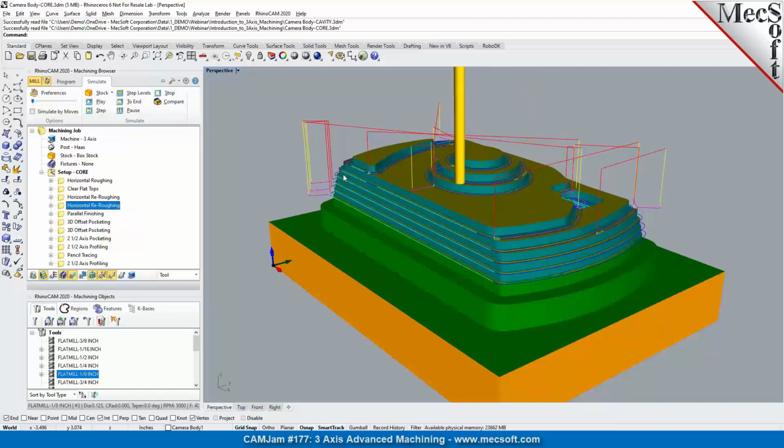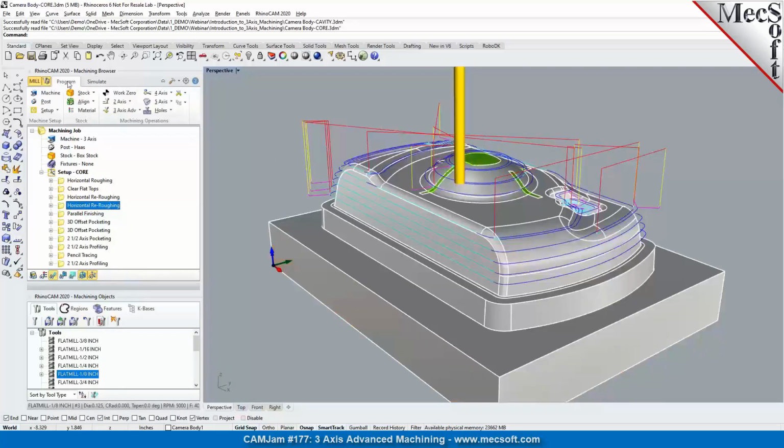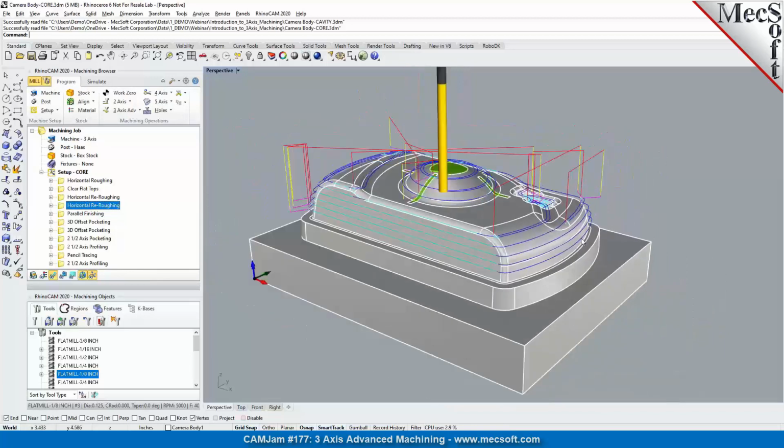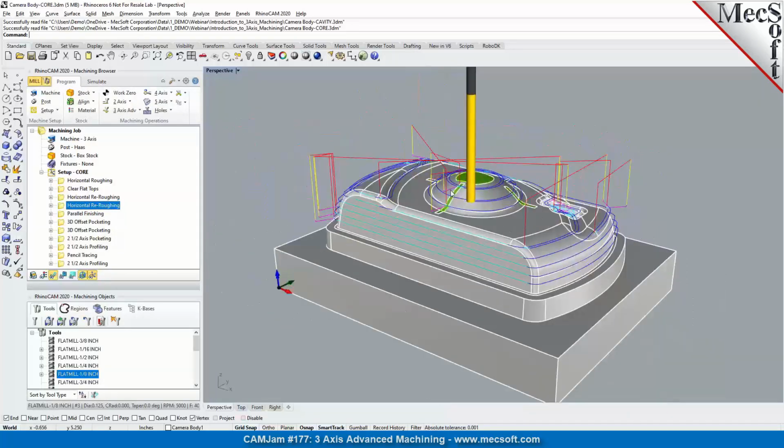Well, there was a question about pencil tracing toolpaths, smoothing, and also the same thing in valley remachining. I can talk a little bit, and then you can add your thoughts as well. As I mentioned, the pencil tracing and valley remachining methods use bitangent contacts.